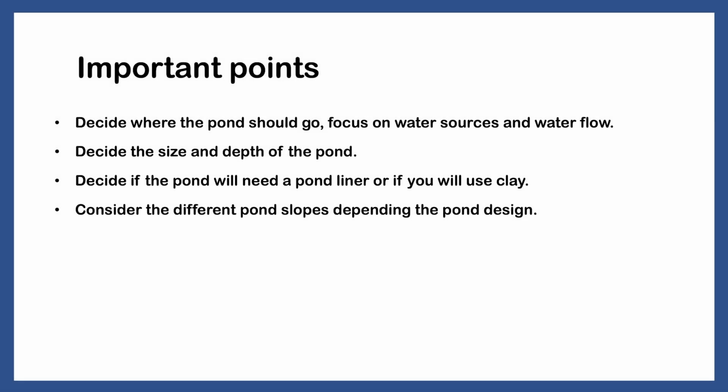Decide where the pond should go. Focus on water sources and water flow. Decide the size and depth of your pond. Decide if the pond will need a pond liner or if you will use clay. Consider the different pond slopes depending on the pond design.